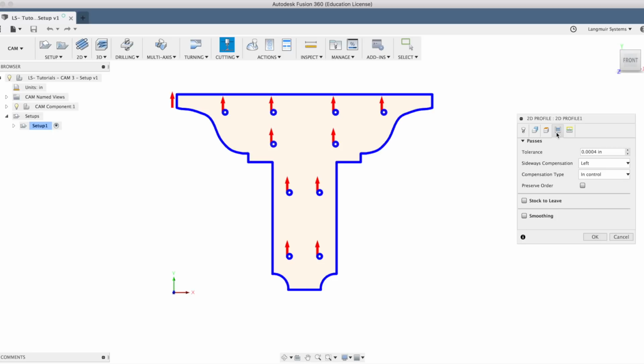In the Passes tab, we'll set a number of important options, the first of which is Tolerance, which determines how closely the toolpaths, moving in tiny linear motions, match the mathematical line. A smaller value here results in larger file sizes, and a larger one in smaller file sizes. This can be an issue for some programmed toolpaths, but this is a pretty simple one, so a tiny value like what we've got here is okay.